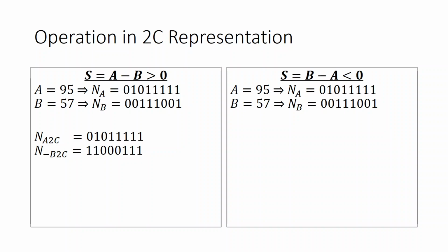We would cover in this lecture the binary number system. We would be looking into the twos complement representation and the ones complement representation, and how we are going to subtract two numbers in them. We are concerned with subtraction because that is the operation that we are not able to do completely using the normal method of subtraction.